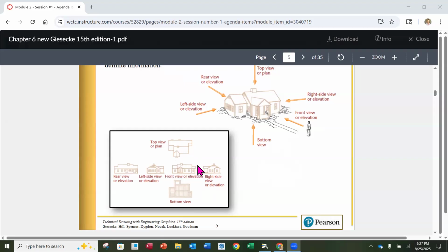It kind of drives me nuts because this front view is just shifted to the right a little bit, but these should be all in line from top to bottom. So orthographic projection means that we have everything all in line across each one of the views. We might see something different in a view, but in the case of, I like the chimney as my best example here, the chimney is straight across in all 4 of those views.